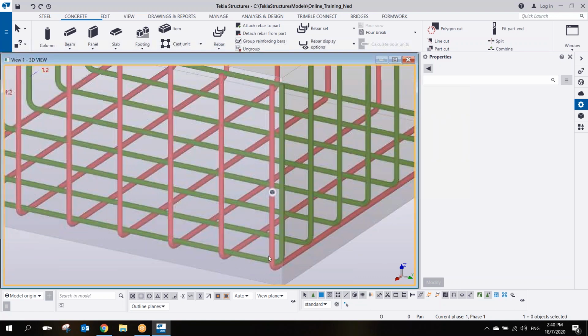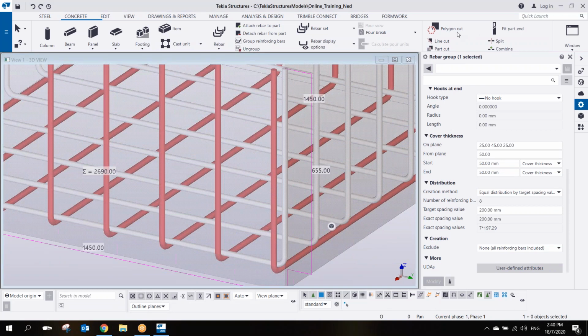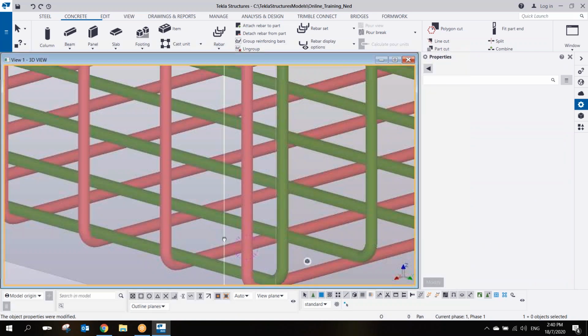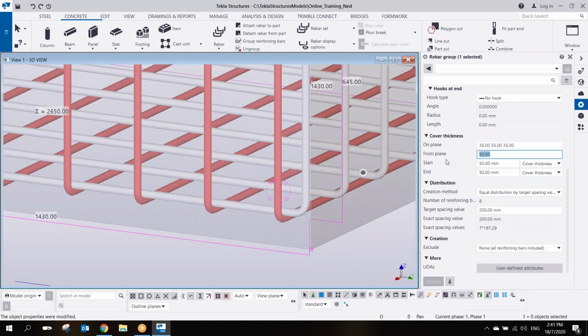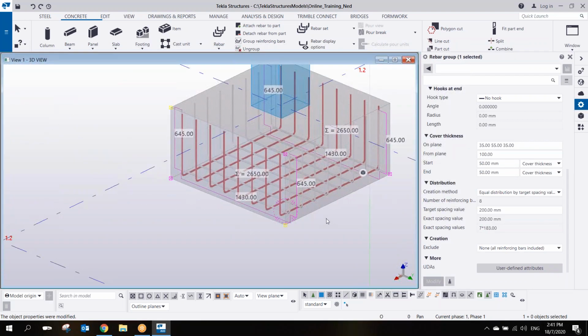Now, let's put the lacer bar. I can add 20, or maybe 30 each here. So let's say here 10 plus 10 millimeter, 10. This one is 55. This one is 35. Modify. And then this one, I'll type here 35, and let's say this one is 100. Modify. This one also, maybe I'll put here 100. Enter.